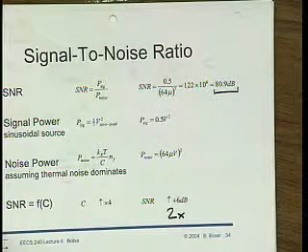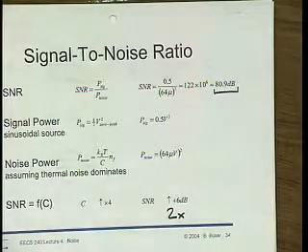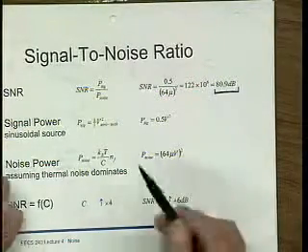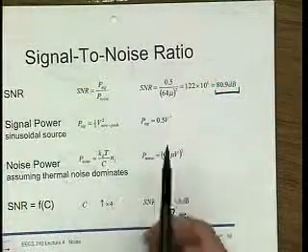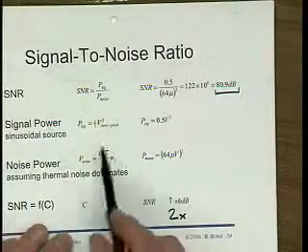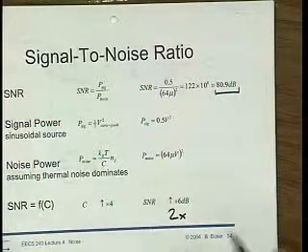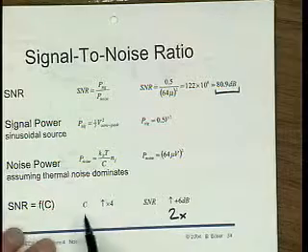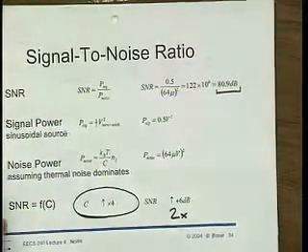Right? So my signal now is twice as large, in volts, compared to the noise as it was before. So that means that either I have to increase this by a factor of 4, double the signal voltage, or alternatively I have to decrease this one by a factor of 4. That means quadrupling C. Right? So for an additional 6 dB, I need to quadruple the value of C.